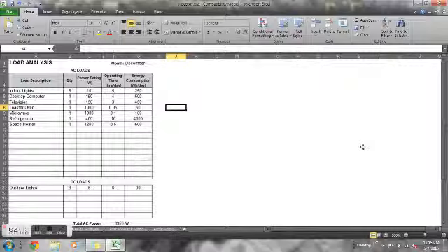And now going back to the first step in sizing a standalone PV system, which is the load analysis. The load requirements determine the size and cost of the PV system, therefore the energy efficiency of your appliances is paramount. For this reason, steps should always be taken to improve the efficiency of your loads. This may involve several factors, including getting more efficient appliances or being more cognizant of your energy use, such as turning off the lights or eliminating phantom load.